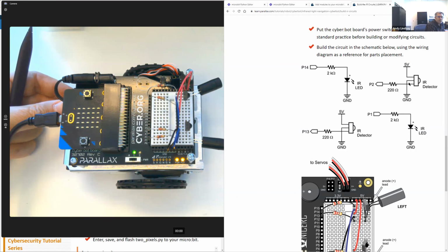The resistor that's going between the IR receiver's output and the IO pin that's listening to the output of the IR receiver is simply protecting the IO pin from short circuits.